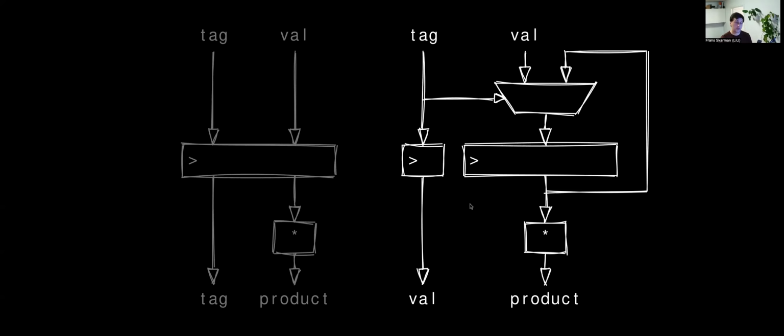In an FPGA, this will most likely get compiled down to an enable signal. In FPGAs, it's a little bit more tricky because usually enable signals are shared between a few registers. So if you have a lot of single bit tag value signals, then you might lose out on some flip-flops. But most of the time you have bigger bit vectors anyway. So while we write the RTL like this, we don't actually get this RTL, and in this case, that's a very good thing. And it does save power.